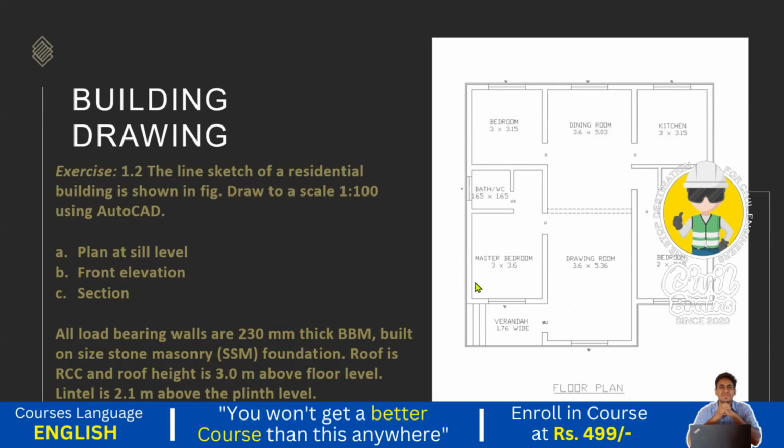Next one, from this inner to inner, there is 3 meter distance. I just take offset and draw the 3 meter wall. Next, after that 3.6 meter inner to inner distance, I just take offset from this one, 3.6 meter, and then I draw one more wall. And next offset I will just take and draw a 3 meter and then draw one more wall. Okay.